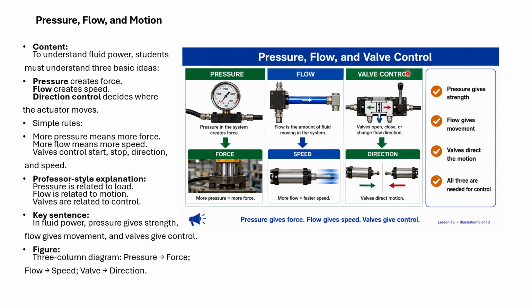Direction control decides where the actuator moves, right or left. Simple rules: more pressure means more force. More flow means more speed. The valve controls start, stop, direction, right, left, and speed.